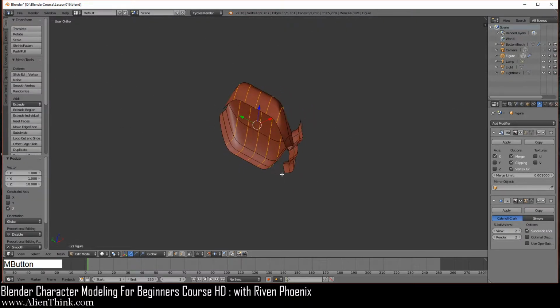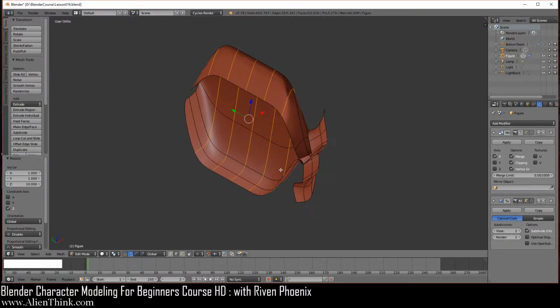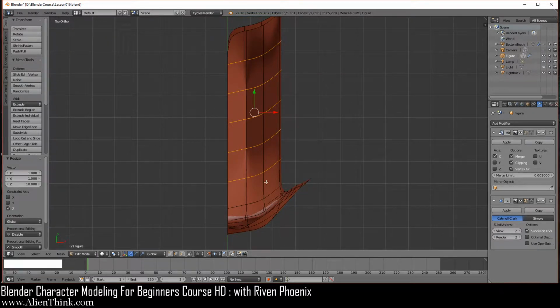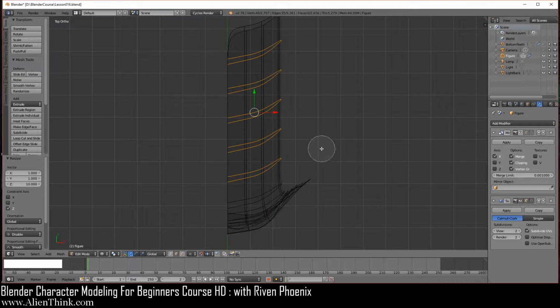And this is going to make it come up like this. Okay, now you're going to press the 7 key to go to the top view. Just zoom in a little bit like this. Press the Z key, then press the C key. Again, with the scroll wheel, you can do the circle select and do the middle mouse button to deselect this. Right click to get out of it.